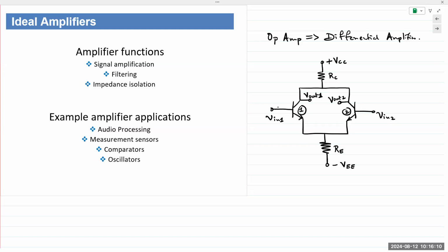When it first comes into our receiver device, that receiver device could be anything, the signal is weak. We perform a little bit of filtering at the front end. Then we need to strengthen that signal and then feed it back into the rest of the circuit. That's where we would use op-amps for filtering as well as for amplification. It can do a 2-in-1 job. It can filter out the signals, allow only a specific signal to enter into our device, plus it can amplify the signal at the same time.